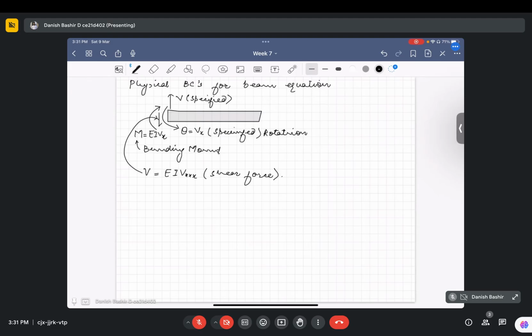So we will use the same variational principle that we used in earlier lectures, the Rayleigh-Ritz method, that is, multiplying the whole differential equation with the variation of the primary variable. Here the primary variable is the transverse displacement. Then we take the integral over the whole domain, find the functional, and minimize that functional with respect to the unknown variable, so that the error is as small as possible. So we will be using the same formulation. Our first goal is to find the potential energy functional